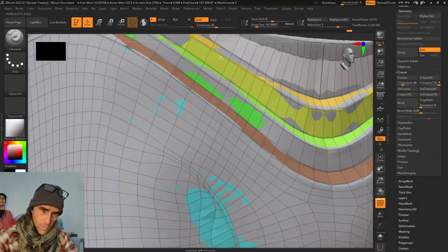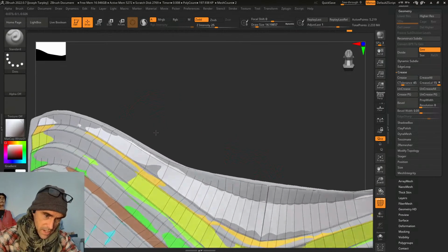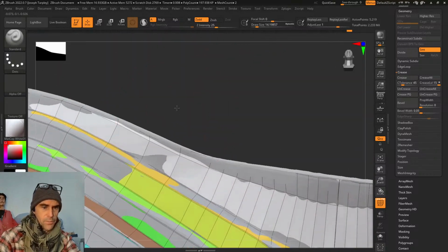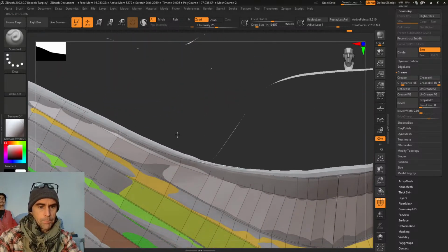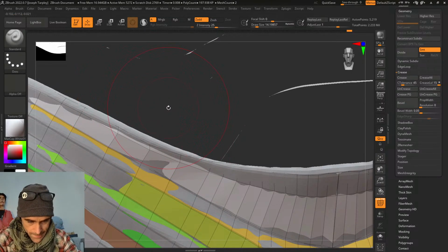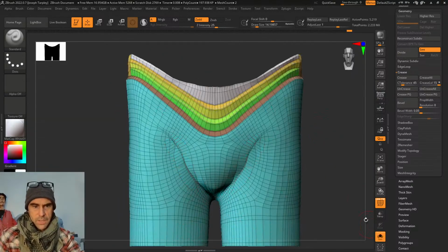Now I'm going to manually move around some of these areas here at the top just to make them line up, because it's really close to the top. With the polygon, ZProject wants to try to push it around this corner, which we don't want. Technically speaking, I could probably simplify. Let me solo this again.